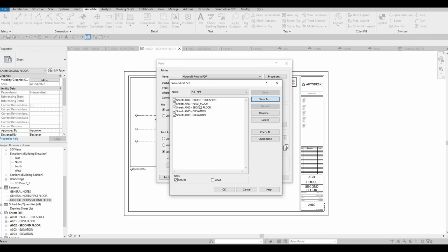And when you're creating revisions, it's easier to create a revision and save as on those ones, so that it's already preset. You can just keep on printing, and you can always add and always update the full set. For example, if I don't want this one to be in my full set, I can uncheck that and then click save. But obviously full set is full set, everything should be checked.